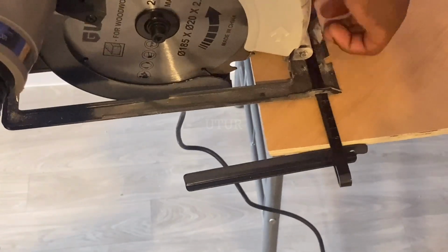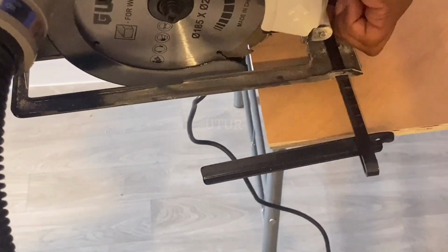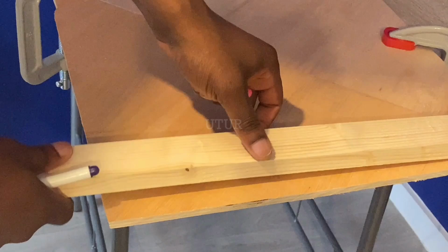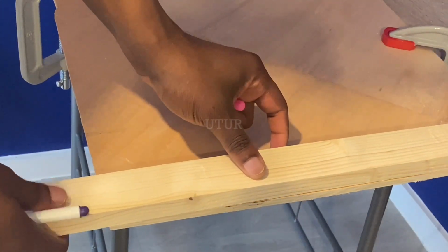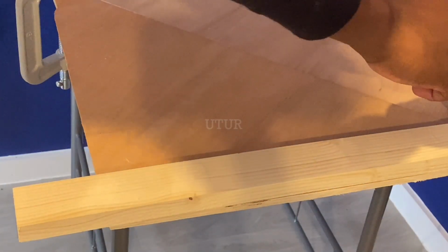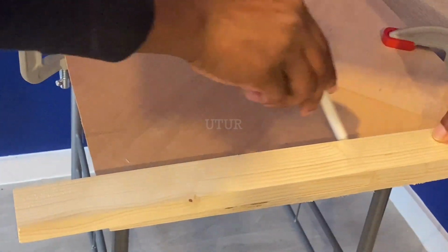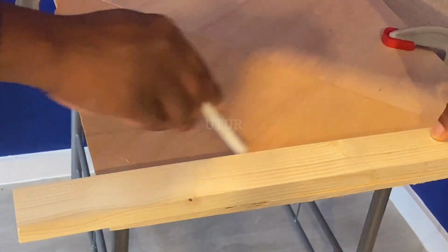And once we've worked out the width of the strip that we want to rip, we can proceed to lock out the lock knob. A rip fence or parallel guide will only make accurate cuts, provided the edge of the plywood board is straight to begin with. And then subsequently, I will be marking out the cutting line for the strip, as saw blades are particularly very good at making linear cuts.